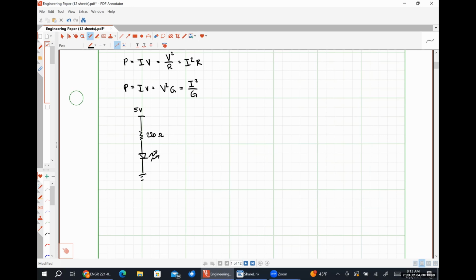What happened if you didn't put the resistor in and you just applied all 5 volts across your LED? It got really, really bright for a split second, and then it ceased to work forever, right? So the resistor was there as a current limiting device to make sure that the LED effectively didn't overheat and burn out. That's all a resistor can really do, okay? All a resistor is capable of doing is converting electrical energy into heat energy. That's completely it, okay? So let me write that down.